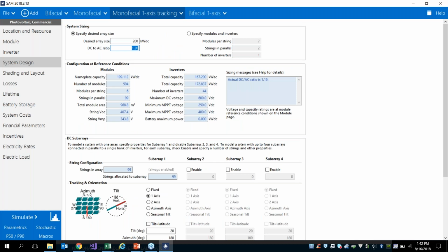We could potentially consider a way to try to consider the rear side. The main challenge there is that the power produced by the rear side is highly dependent on the system configuration. And so even on module manufacturers' data sheets, you don't always see a nominal capacity for the rear side, since it's so dependent on the albedo of the ground and how the rows are laid out.